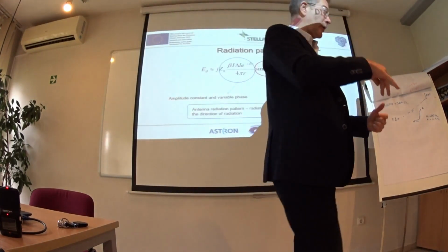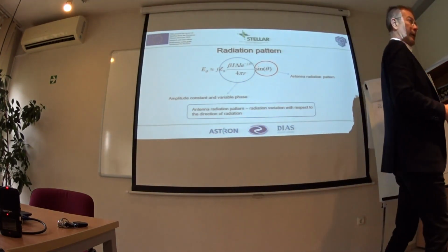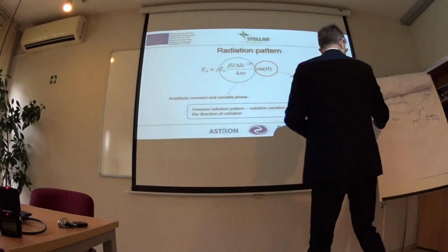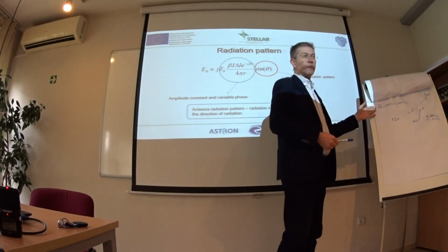If you change the medium from free space to, for instance, Teflon, the relation between these vectors will change. The wave will still propagate, but the ratio between these two vectors will change. And the ratio between these two vectors is called the characteristic impedance of the medium.